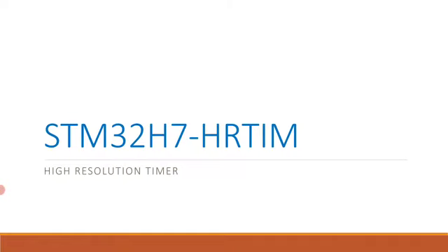event conditioning, external event management, output stage, chopper, and burst mode controller, fault management, numerous fault management options, and triggering ADC with HRTIM, that is high resolution timer, digital to analog converter trigger, register update, and interrupt vectors, namely 7 vectors and 85 sources, and DMA requests, that is 6 requests and 77 sources, and low power modes, application example, and related peripherals to that.